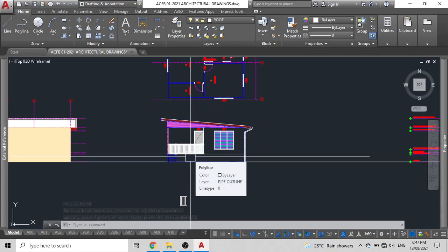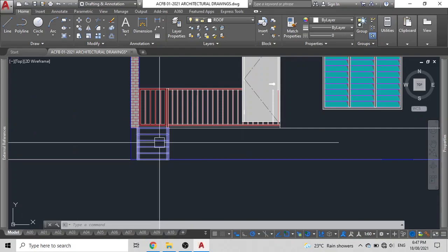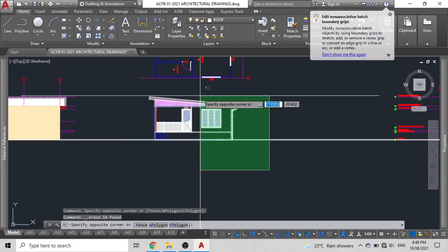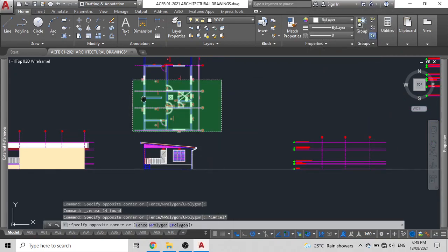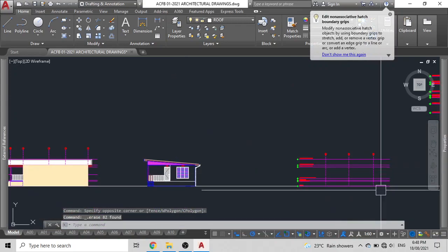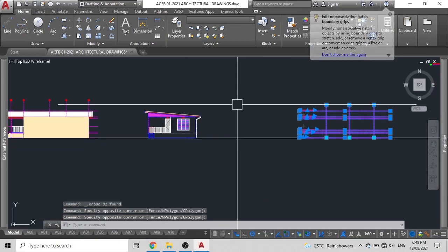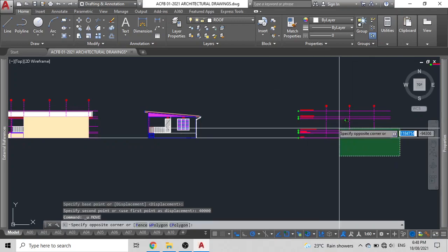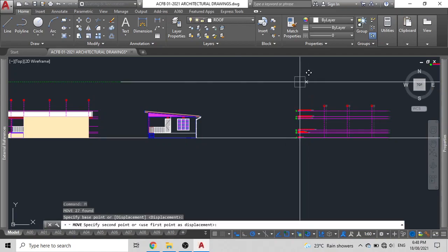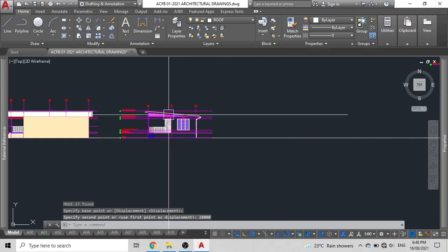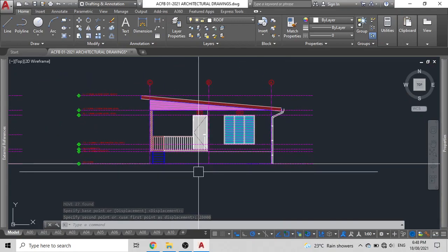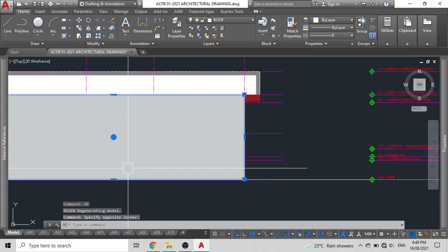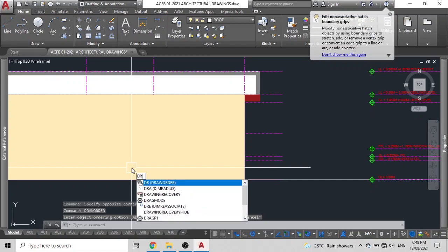Now you can see that your actual elevation is starting to take its shape. So what we'll do, we'll just bring back all of the grids and everything, and maybe I think it's best we'll delete this, because now this referencing is done. Remember that key distance that you had placed there? Oops, it's not 40,000. My apologies. It's 28,000. And voila, that's it. So since all that is now done, ensure that your elevation is actually true to its view, and then you can start to plot and publish the drawings.